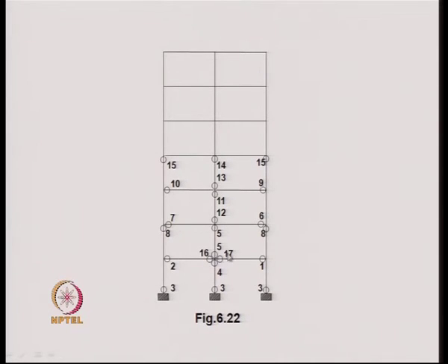If this kind of situation does not take place, then perhaps more plastic hinges can form in the structure, and the calculations may be continued further, or the incremental displacements can be provided, and the solution procedure can be carried out till a desired collapse state or collapse mechanism is formed by the plastic hinges forming at different cross sections, without a situation of premature failure like this.